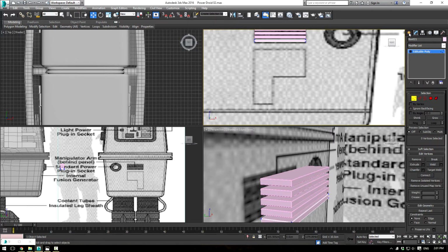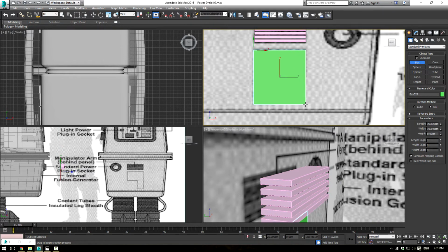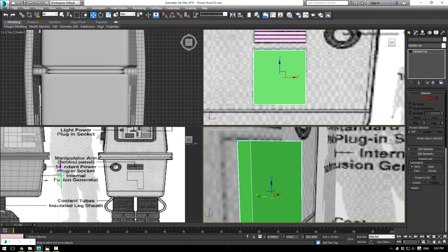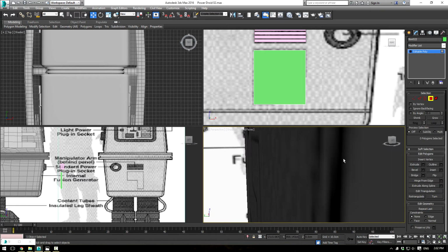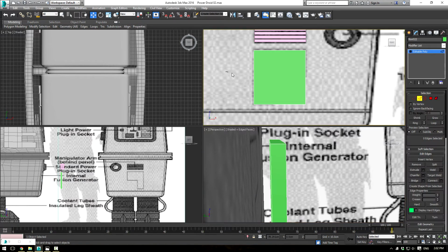we'll just go ahead and create a new one here. So make a box. Okay, give it some thickness. Convert it to an editable poly here, and let's go ahead and just delete the back polygon there. Grab the front, you press Alt-X just so we can see what we're doing and connect it. That's actually pretty close, so just bring it up. Okay, grab this one, connect, and slide it into position.